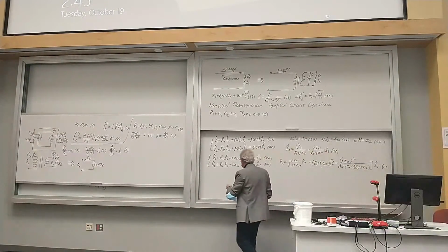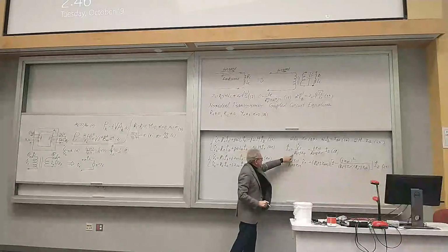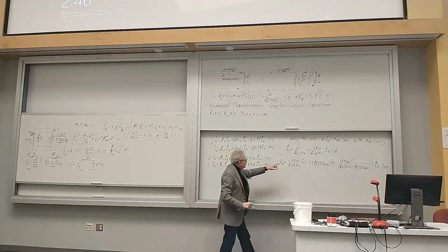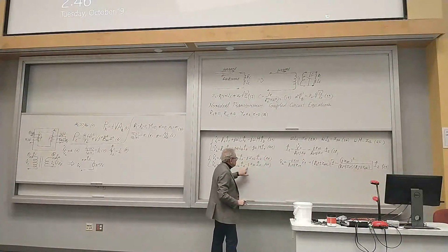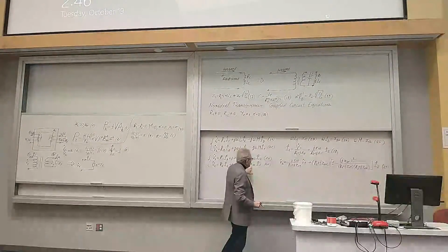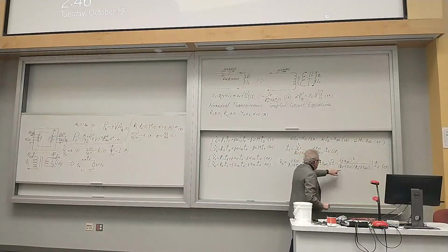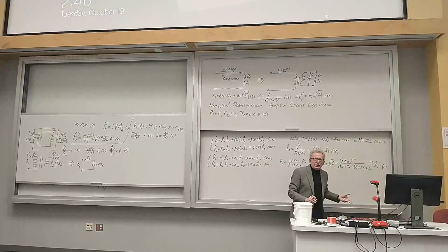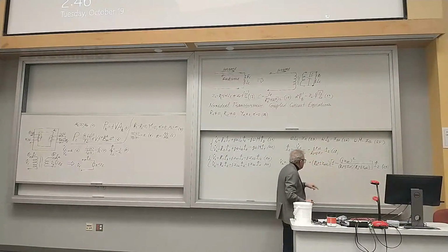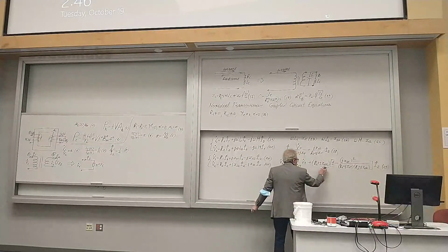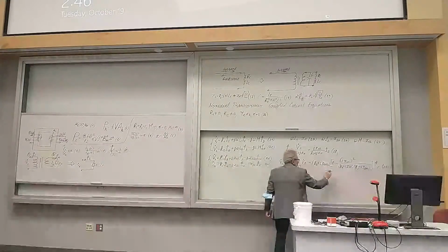Again, how did I get this expression? When I substituted this first term, it is here. It's multiplied by negative j times x sub 1, 2. Then I substituted this term. It goes with sign minus, yes. It's multiplied by x sub 1, 2, yes. And divided by, so it will be jx sub 1, 2 squared divided by this. And I put this in the denominator because if you multiply it by two terms, it will cancel because I decided to factor this one. And the last two terms are because of this one. It will be r2 plus jx sub 2 times I sub 2.